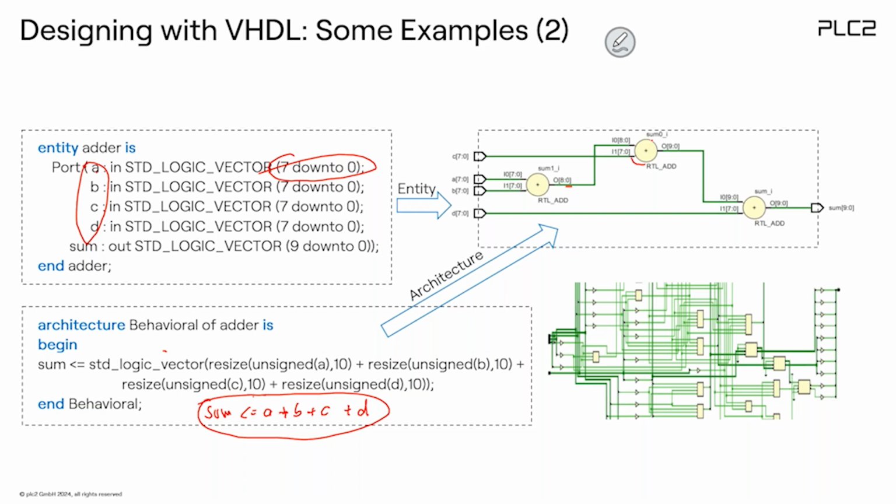You just need to understand that whenever you add 2 values, A and B, and the values are 8-bit, for example, don't expect, the human will expect, but not VHDL. Don't expect the result will be 9-bit.